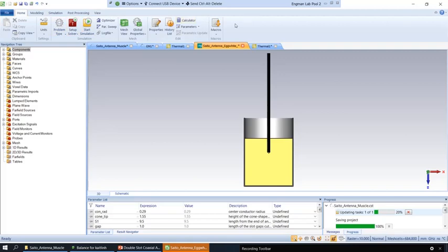Okay, so to summarize, you can use parameter sweeps, which are a little bit less fine of a tool, but a little bit less difficult to use. You can use an optimizer, which does a lot of the work for you, but can run for a long time and requires you to understand what the optimizer is doing in order to set up a decent optimization. And then finally, when you're doing optimizations, you need to be conscientious about the values you choose, so the range that you give it, and you also need to be conscientious about the mesh value. And remember that you can still get trends, you can still see what values look like they're going to be better, even if your simulation is not the most accurate thing in the world. So just make sure you check your mesh properties before you do the simulation.